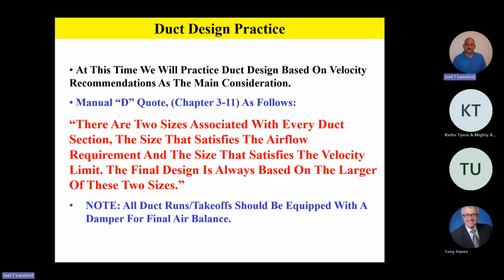Now, we're also going to ask that you please note that all duct runs, takeoffs in other words, should be equipped with a manual damper for final airflow balance. Unless you've got a duct system that is absolutely perfectly designed as far as the length of the duct, we find that in most applications a method of balancing the airflow into each conditioned space is going to be very, very important. So we recommend that during installation, you plan on a damper on each takeoff so that you can do final airflow balance when you're done.